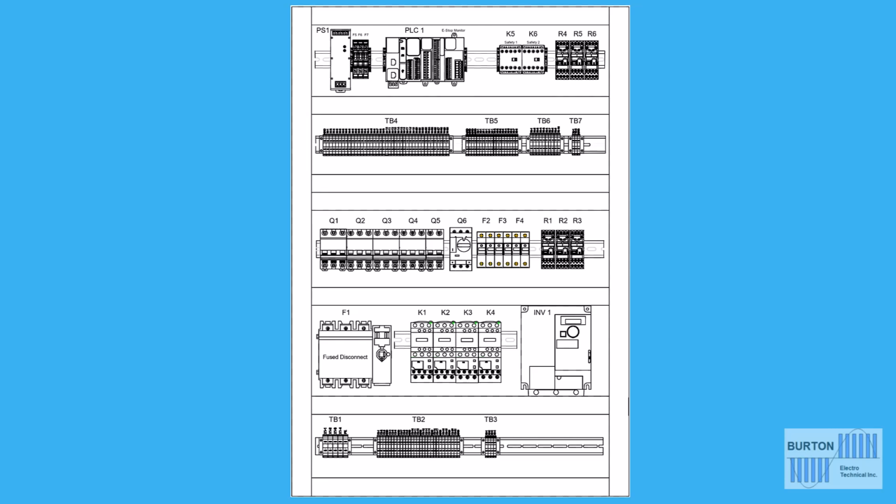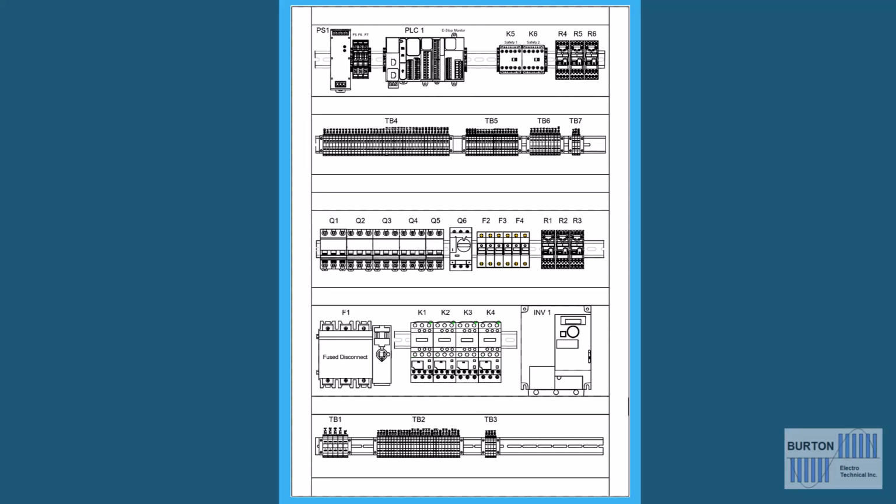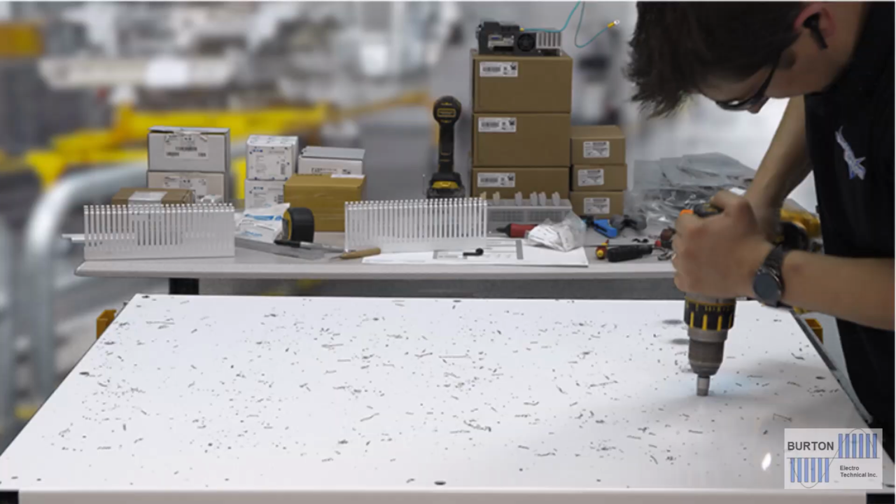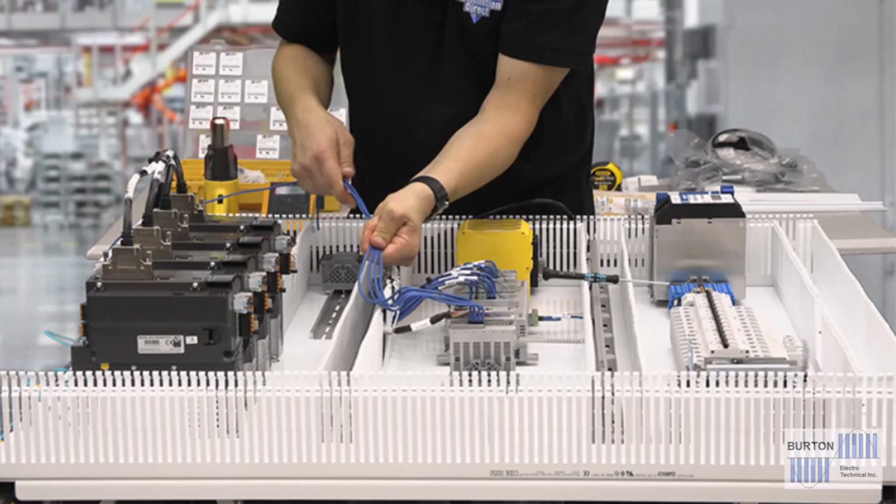Large backplate layouts are drawn in CAD programs. They show all of the installed equipment, including the wiring ducts. Layouts can be plotted to scale or used as a reference drawing for panel builders. Equipment can be mounted, and most of the wiring can be done before the back panel is mounted into the enclosure.